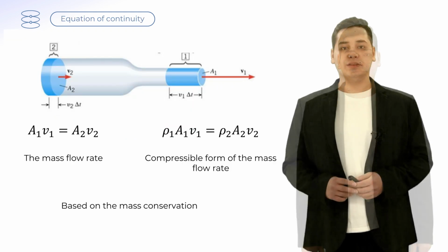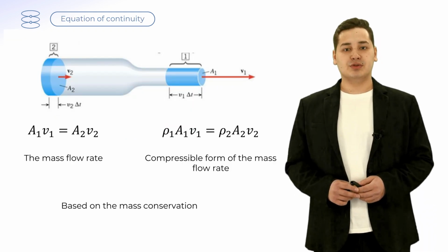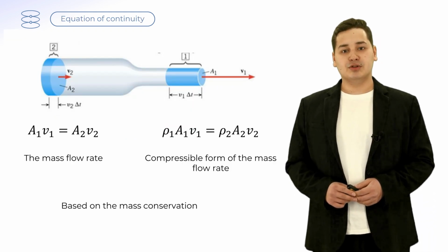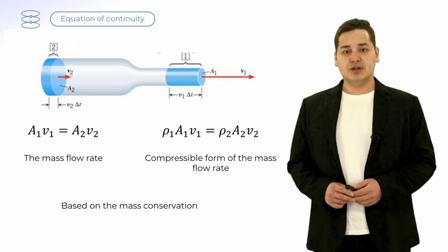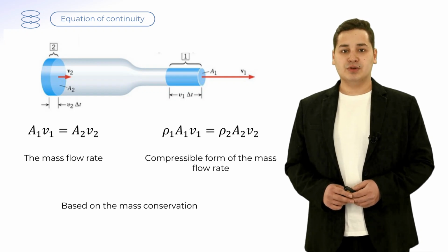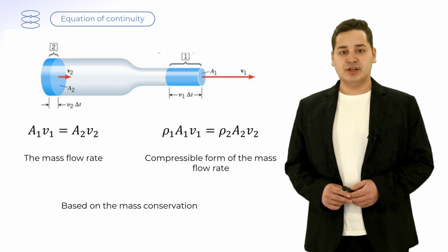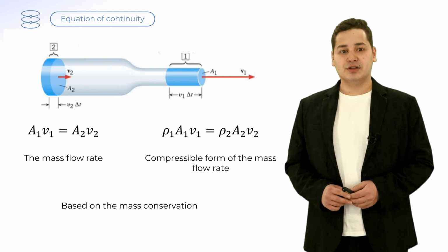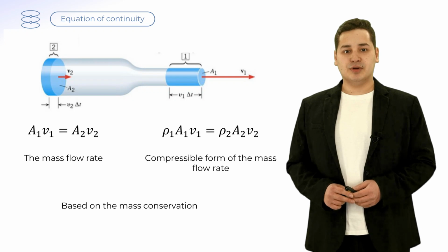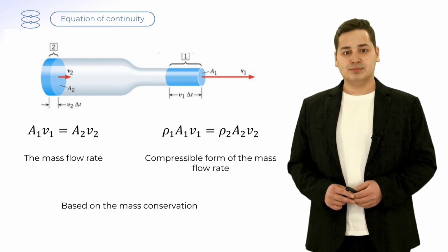conservation of energy. The conservation of mass gives us an easy way to determine the velocity of flow in a tube if the density is constant. If we can determine or set the velocity at some known area, the equation tells us the value of velocity for any other area. The quantity density times area times velocity has the dimensions of mass divided by time and is called the mass flow rate. This quantity is an important parameter in determining the thrust produced by a propulsion system.